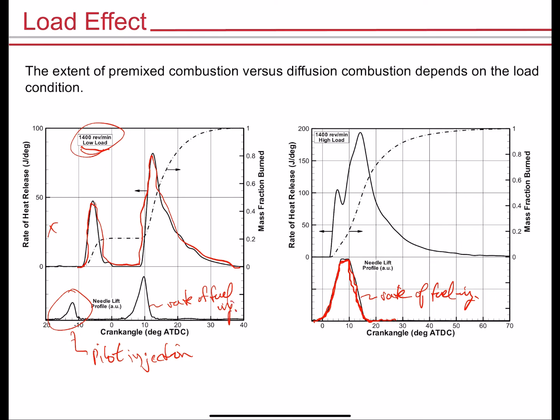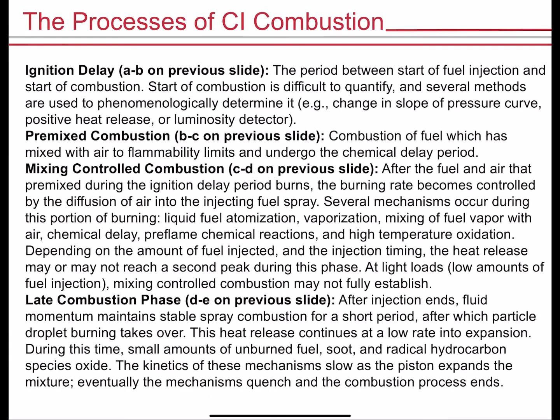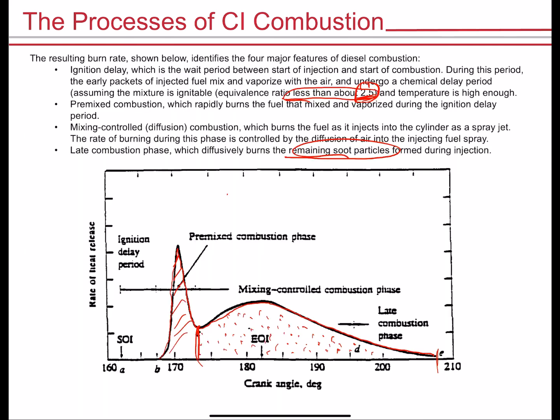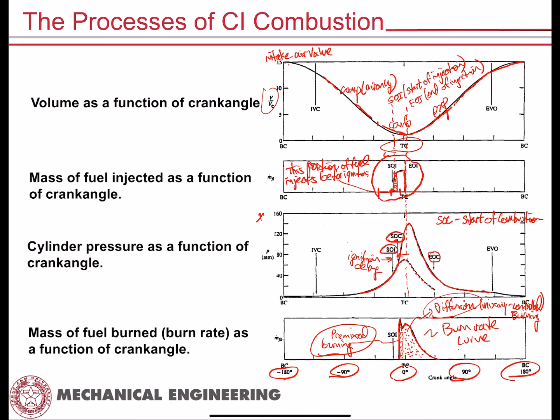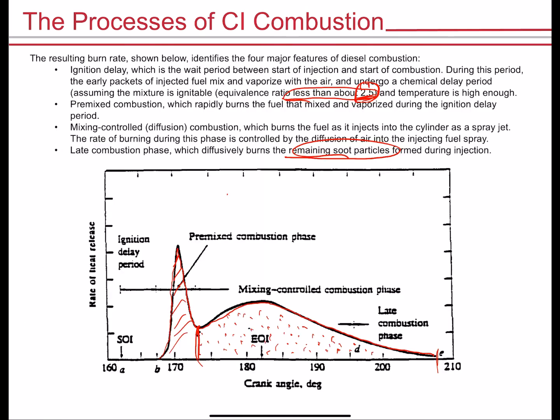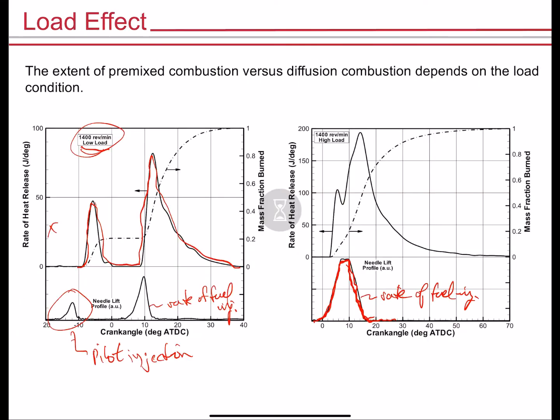If you look at this curve, what you'll notice is that it looks real similar to this one right here. You see the similarities where you have a rise in the fuel that's injected, it stabilizes, and then it drops as you end injection. That's exactly what's going on here. You have a rise in the rate of fuel injection, it stabilizes, and then it eventually drops.